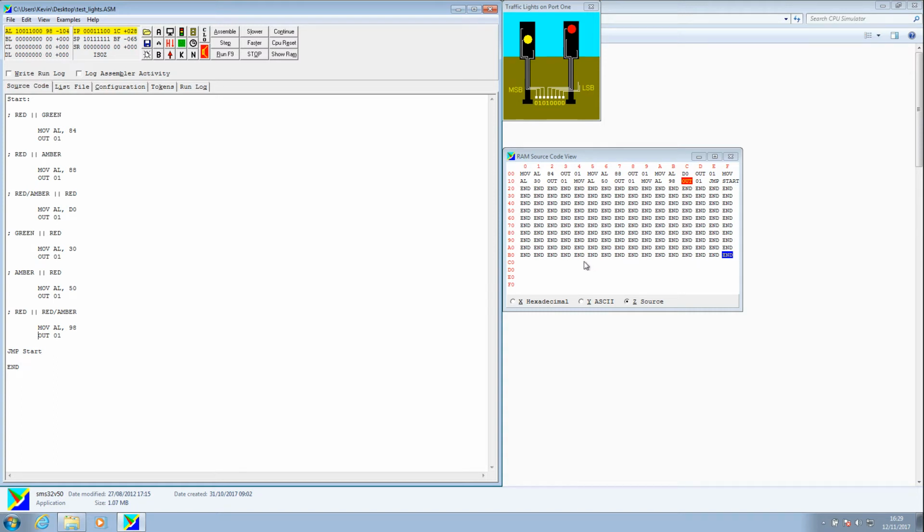What we're going to do is create another little tiny procedure or program which is going to run at the top end of this source code RAM editor to keep it out of the way, and that will use a simple loop which will go around decrementing by 1 until it hits 0, and then it will jump back into where the program was originally running. So it's really just a timing loop. So let's see how we would do that.